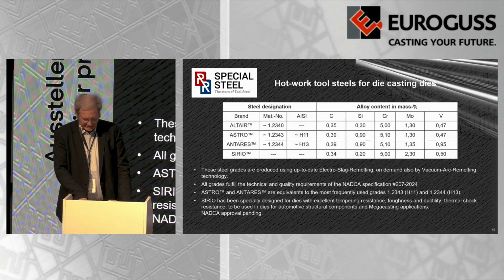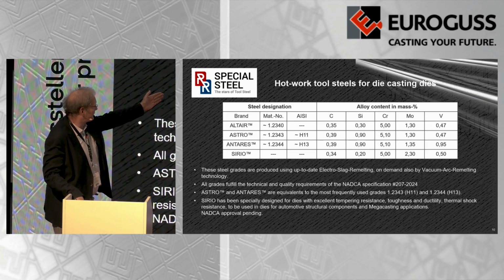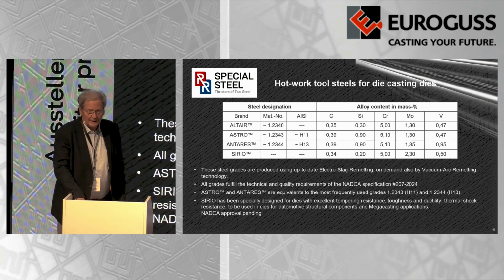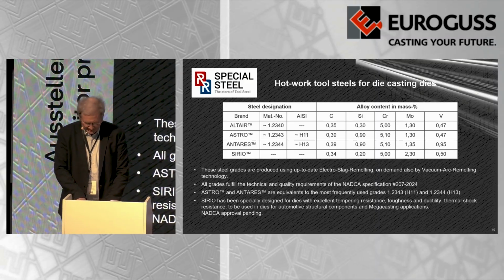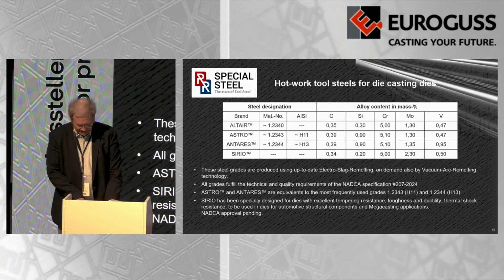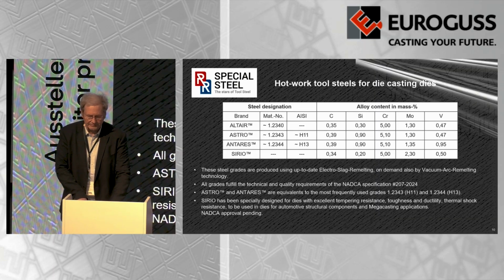Astro and Antares are equivalents to the most frequently used grades 1.2343 and 1.2344, and Sirio is our own development, designed with excellent tempering resistance, toughness, and high temperature strength for a good thermal shock resistance.